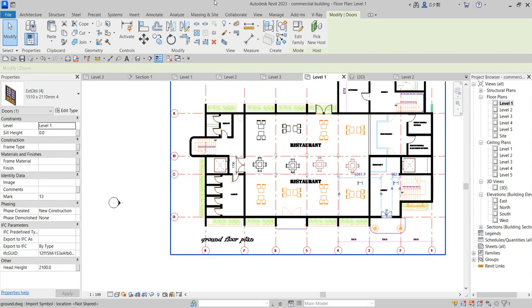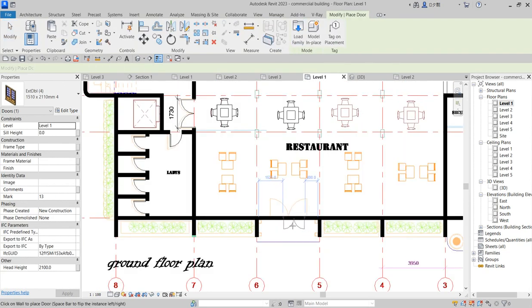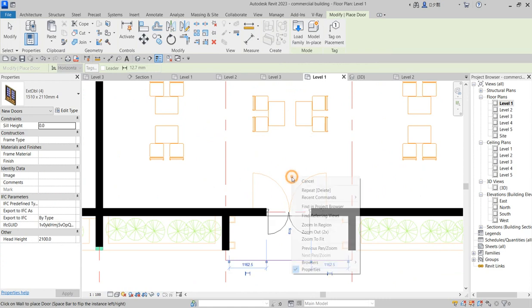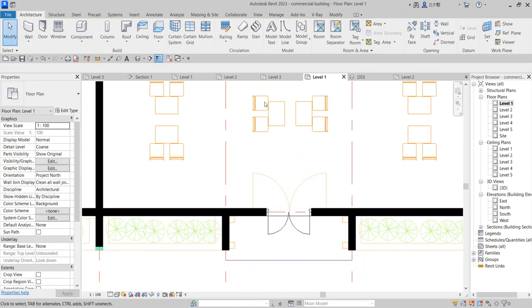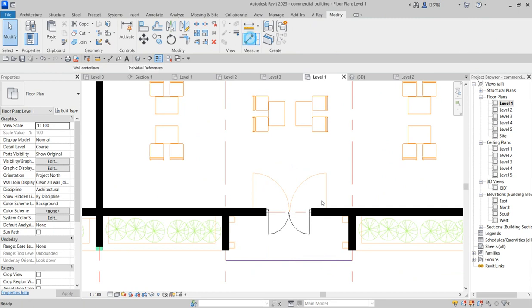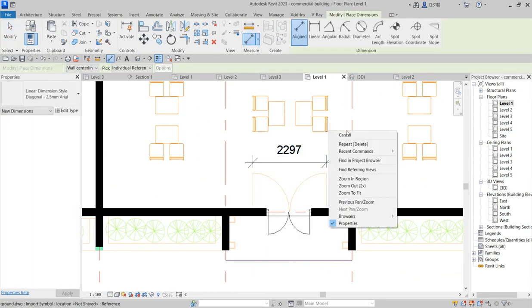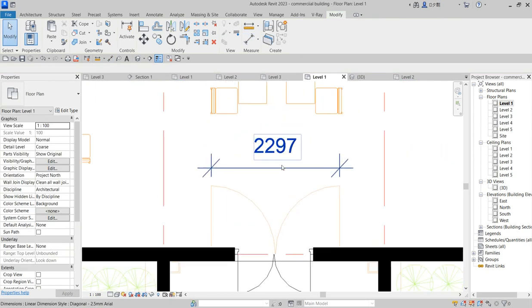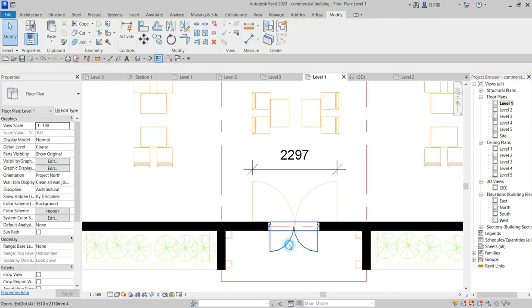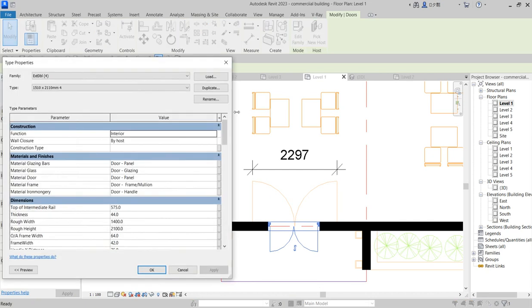So like this, you say create similar. This door is bigger. You can decide to duplicate it. Know the measurement of what you want to do. You want to work precisely based on certain levels. So like this one is say 2000, that is 2300. So click, duplicate